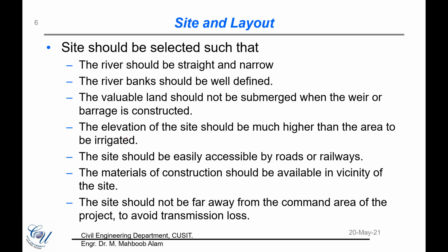Material of construction should be available in vicinity of the site. This is also important requirement. Otherwise, we will be consuming a lot of resources in transporting the construction material from, let's say, far away places to this diversion headwork. So more or less the construction material should be easily available and available in the vicinity of the site.